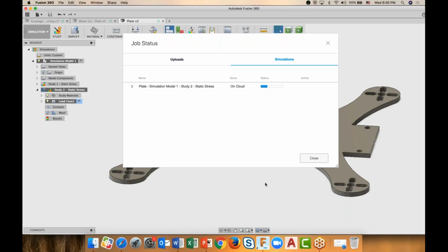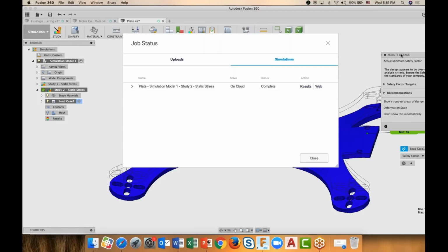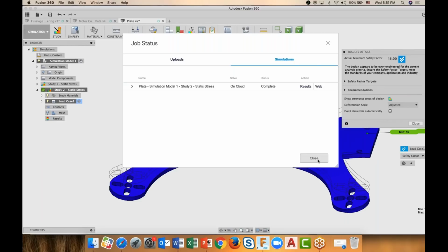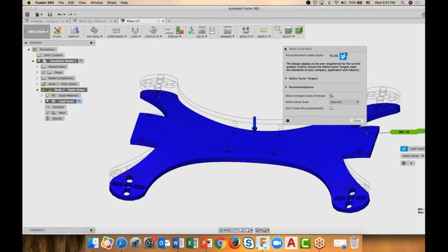Yeah, so I put an answer into the questions there. My understanding, and I have not done this myself, is that once you complete your animation, you can then go back and render it. The problem is that inside of Fusion, you're given, I think, 16 cloud credits that you can use to render at any given time. So you can use an unlimited number of cloud credits, but in 16-unit intervals, and rendering an animation uses way more than that budget. So my understanding, and again, disclaimer, I'm not 100% sure on this, is that you would be able to do it assuming you bought a whole pile of these cloud credits. I think the default covers any static image, so anything you're going to do in the rendering workspace, you should have enough cloud credits for. I think rendering an animation is what puts it way over.